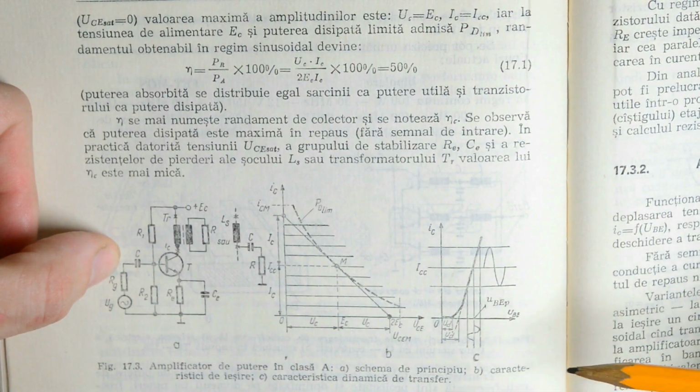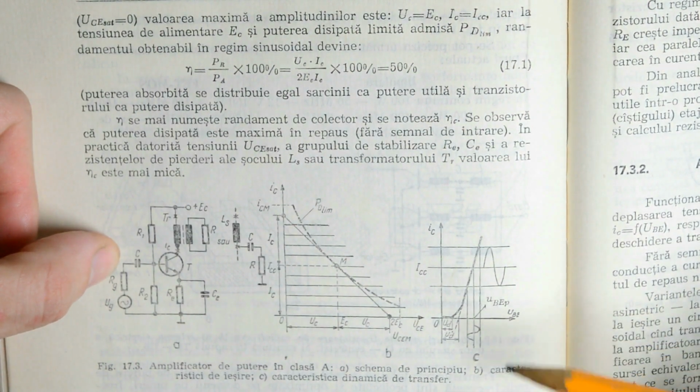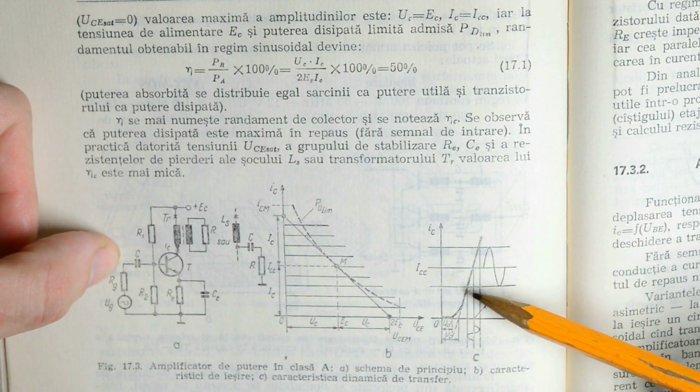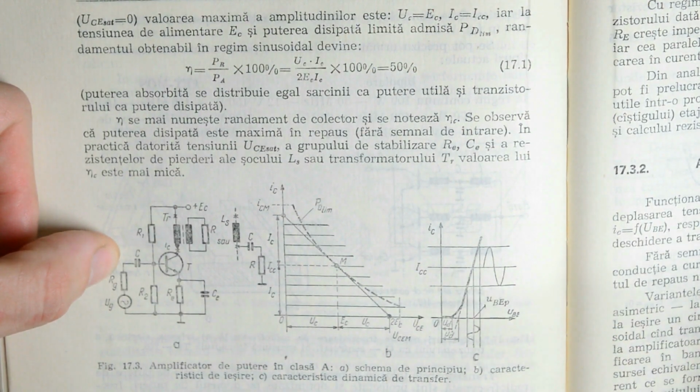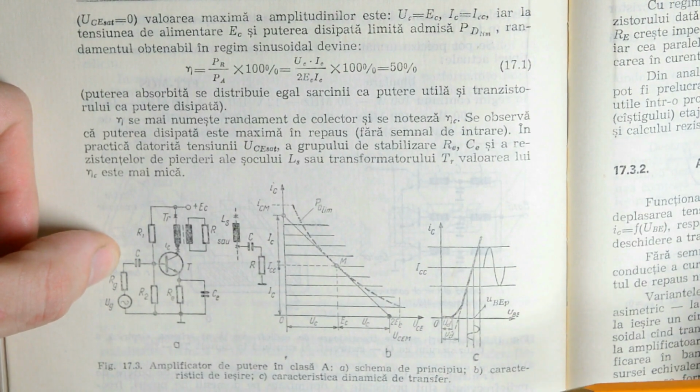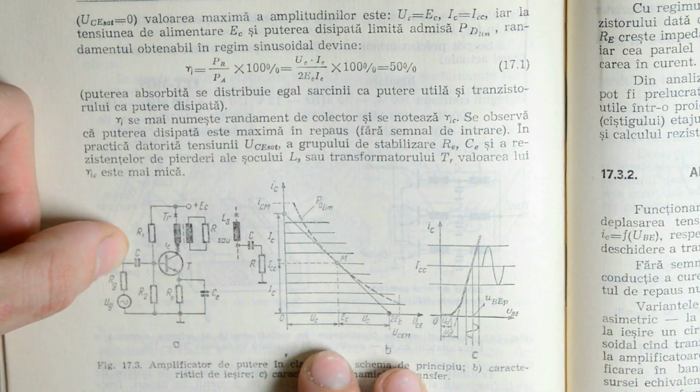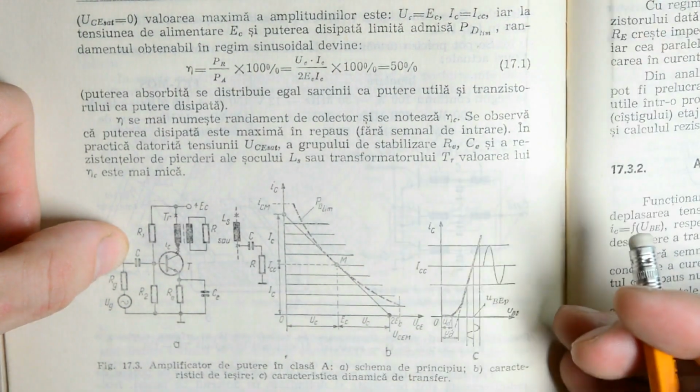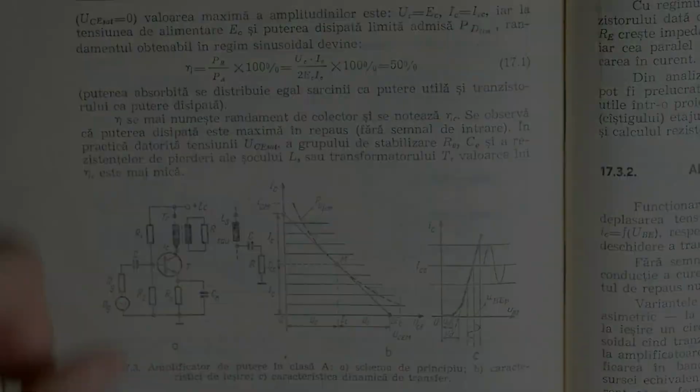So this will make our amplifier very linear. We're only using a single transistor in its linear region, so there's nothing that would distort or modify our signal. But it's also a very inefficient way of using a transistor because we always have current going through it. So we're always wasting some power. So let's see how this circuit works in reality by simulating it.